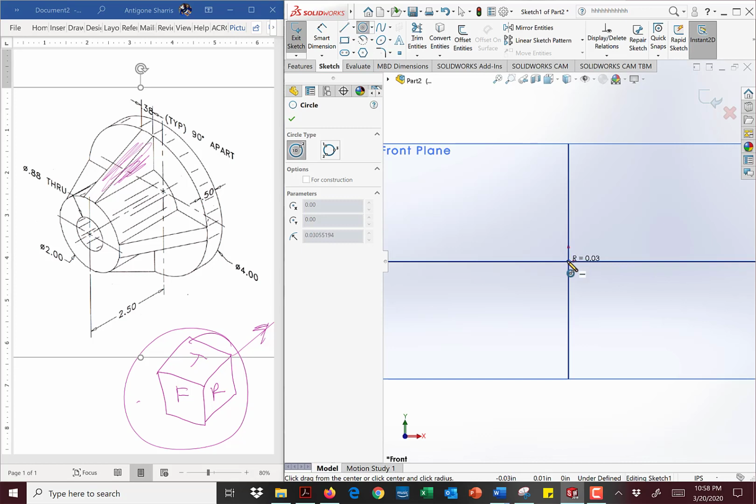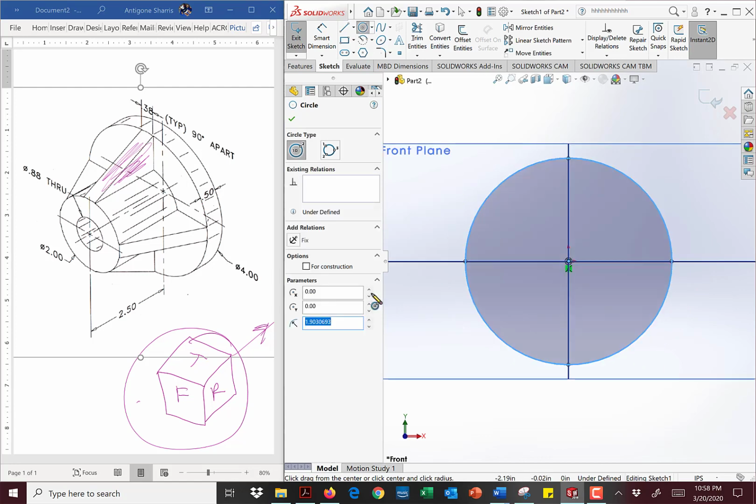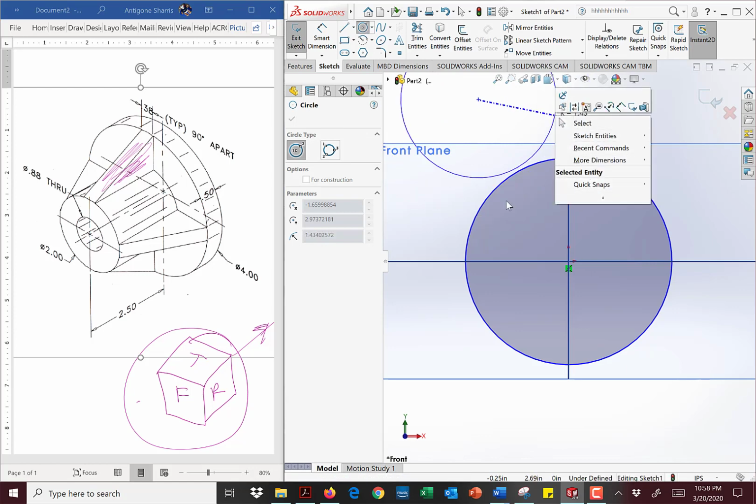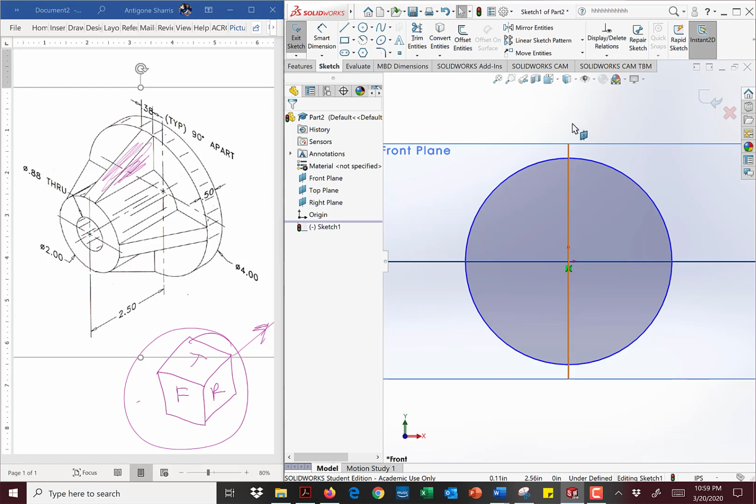See that? I'll stop again, just real quick. See the constraint and go out. And then I can go anywhere. I'm going to click out here. I will not change this dimension here, because changing it here does not actually constrain this sketch. Okay, very important that we constrain this sketch. If you accidentally click somewhere else, right mouse button and new select. Get away from there. Okay, so there's my sketch.